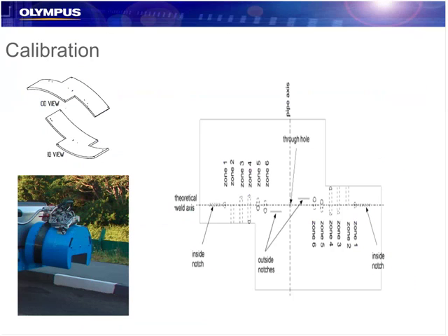So here's a typical calibration block shown here, for onshore mainly. We use what we call a Z block. To reduce the weight of it, we basically have a Z shape. One side is basically upstream, downstream. And we'll place this in a dummy pipe often to reduce the weight, because depending on the thickness, the block could be very heavy.